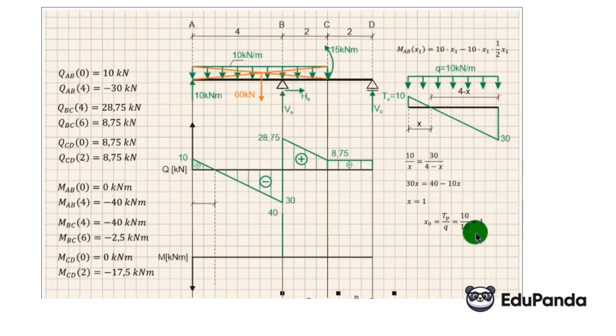Okay, now we know that coordinate 1 is the coordinate for which x0 occurs. So now we substitute into our formula for x1 simply 1 and calculate the value. And it comes out to 5 kN times meter, which is a positive value. We mark it. And as I mentioned, under a continuous load on the moments graph, the graph is a parabola. We mark the maximum value.